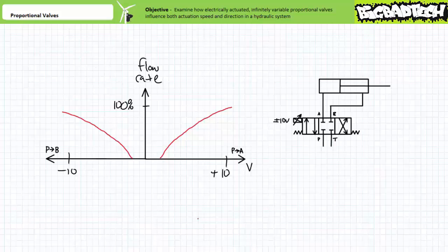Proportional valves, despite their superpowers and associated expense, largely behave as would a regular flow control valve in that variations in pressure upstream or load-induced variations of pressure downstream would also serve to change the observed flow rate through the valve. Related to this phenomenon, the super observant and fastidious among you will note different flow rates for the straight-through and cross-connect positions given the same applied voltage.